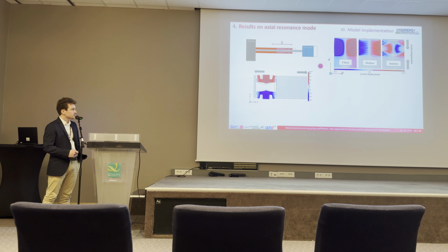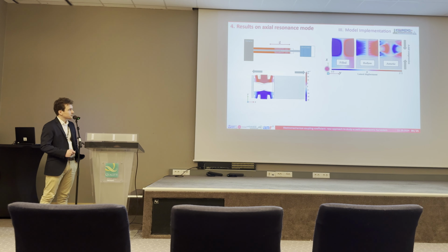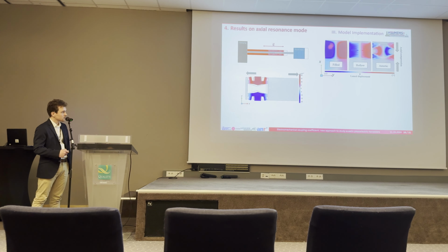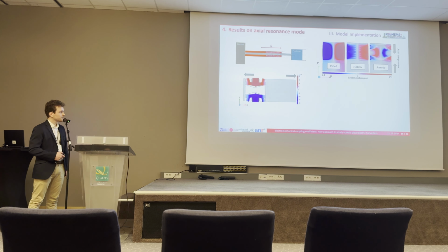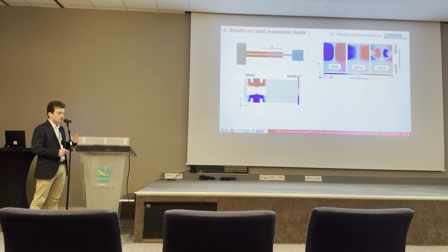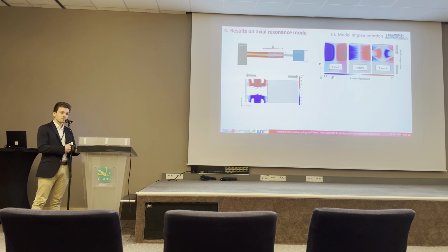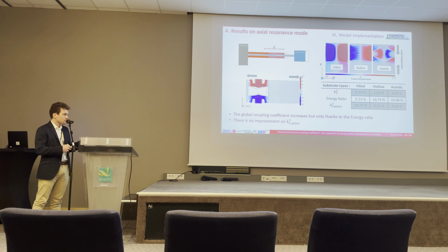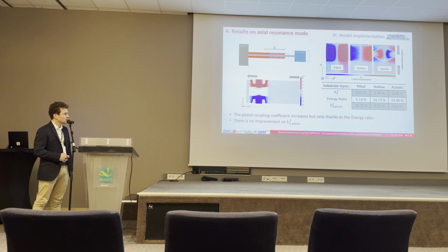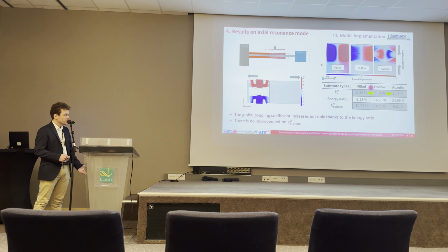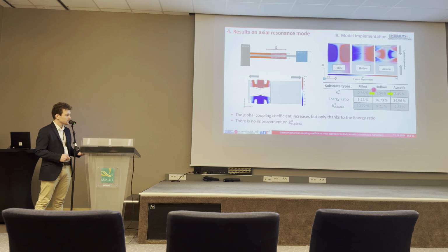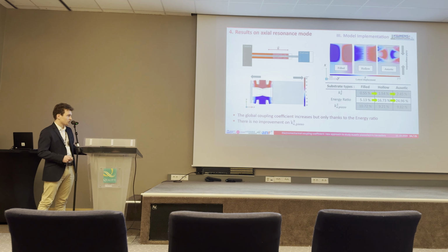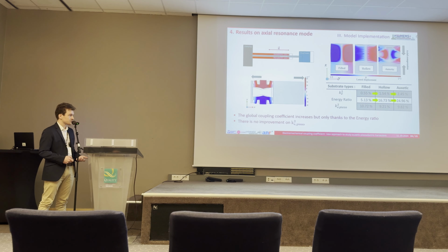Here are the results with the piezoelectric layers. So we see that on the filled substrate, we have a kind of displacement, which is inverted for the auxetic substrate. We have to note that it was really hard to get auxetic behavior on the piezoelectric layers because of the piezoelectric stiffness. And here are the results, values. So we see that the global coupling really increased by changing substrate, so did the energy ratio, but not the material coupling coefficient.